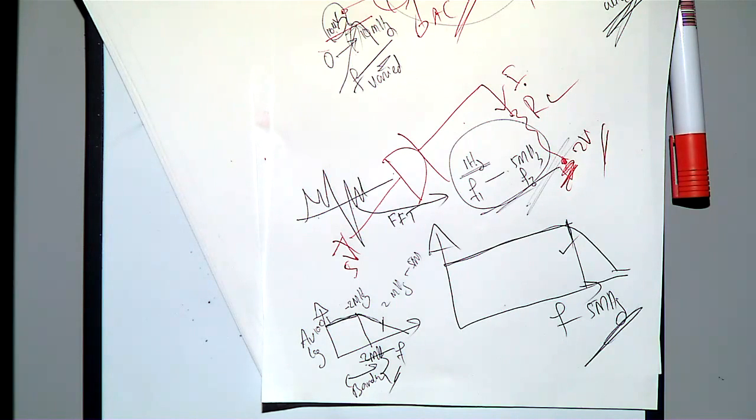A phone conversation differs from a face-to-face conversation, as you might have noted. Why? Because your natural voice is 20 hertz to 20 kilohertz, that is our audible range. But when you talk to someone over the phone, the sound might be slightly different. Why? Because when somebody is talking, it may be from 20 hertz to 20 kilohertz, but your phone has only a finite bandwidth, maybe 400 hertz to 3.5 kilohertz. So you are throwing away some frequencies, and then your sound may be a bit different.